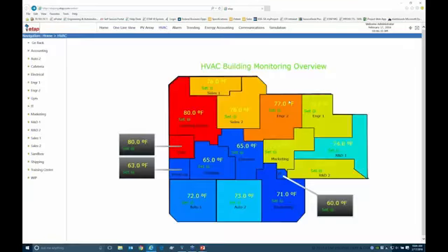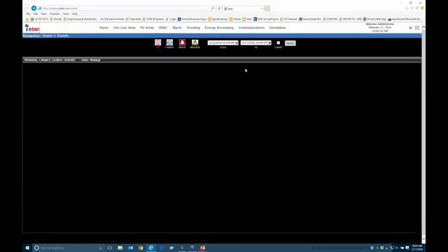Other things we can do in this dashboard include the HVAC monitoring, so you can see what's going on with temperature in different parts of the building. As you can see, the setpoint is 71, and we know that because the air conditioning is running, so it's measuring about 71 Fahrenheit here. And there's air conditioning running in the cafeteria too, so that's sitting at about 65 Fahrenheit. So that kind of confirms what we're seeing with the electrical side as well.